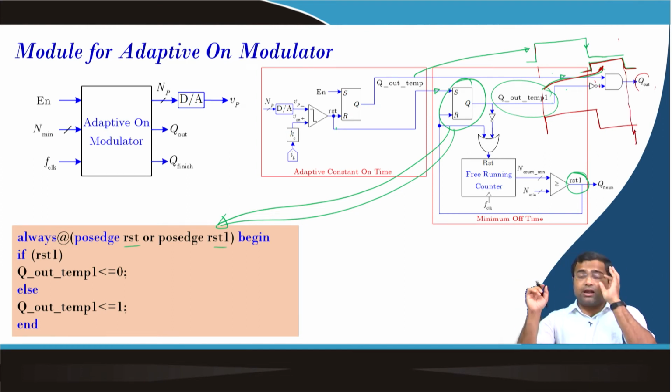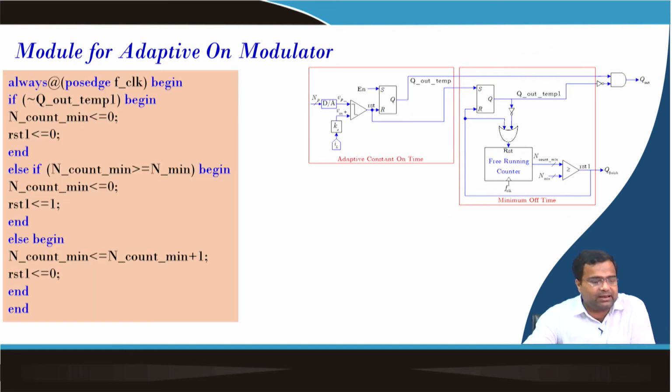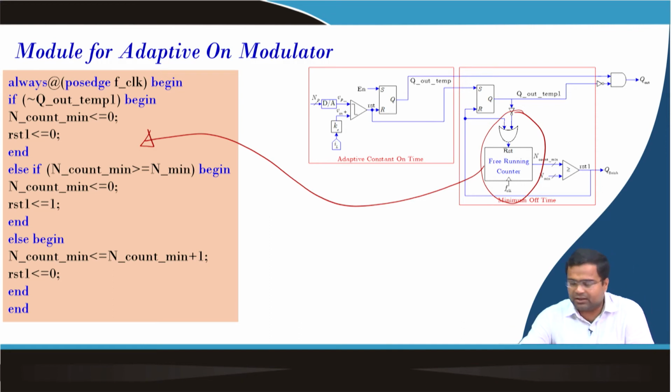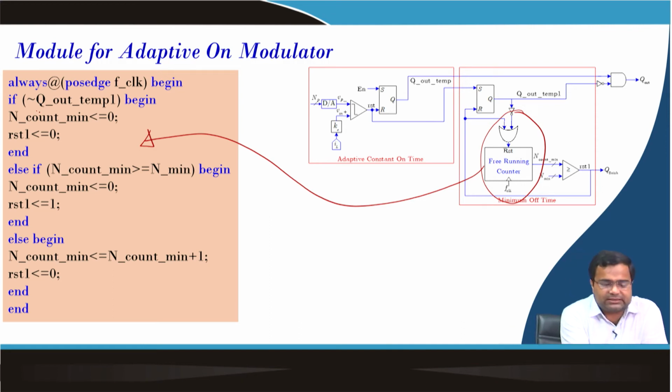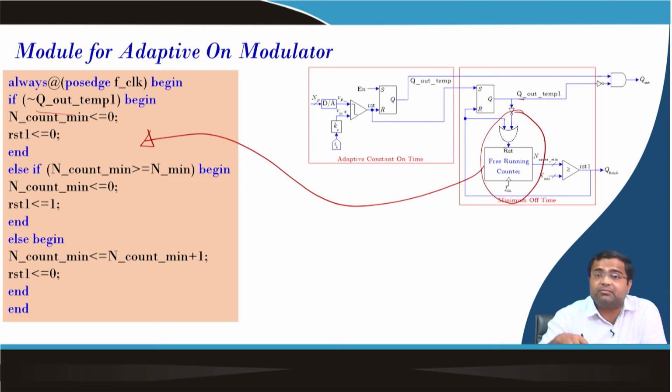Now, you can turn on again if it is required, but until this time it cannot turn on, as there is a minimum on-time. Okay, and this logic is enable and disable. It will check at the clock edge. So, this particular block is implemented here. You can say whenever the reset is low, that means if this is high, then only the counter will be incrementing.